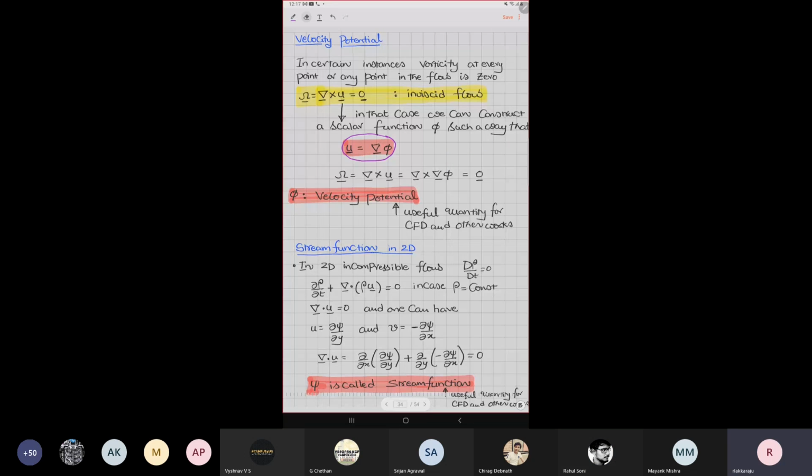And when you are going to learn CFD, computational fluid mechanics, this velocity potential becomes one of the basis. Most of the aerodynamics problems, they don't solve the Navier-Stokes equation. They solve something named Euler equations, where your vorticity is already chucked out. In that case, this velocity potential becomes very friendly to handle, to get the information.